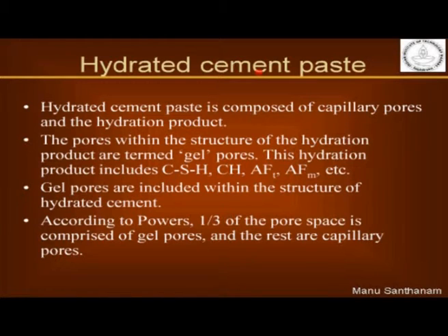Now this is the most important fact as it relates very well to how your concrete structure finally looks and how concrete finally behaves when it is exposed to different sorts of loading or different environmental conditions. Okay, so hydrated cement paste is composed of capillary porosity and the hydration products. You have porosity in the system because when cement hydrates and reacts with water, there is no way you are going to fill up the entire volume with solid. So there will be a lot of porosity that is still vacant, zones not occupied by solid, and that is called capillary porosity.